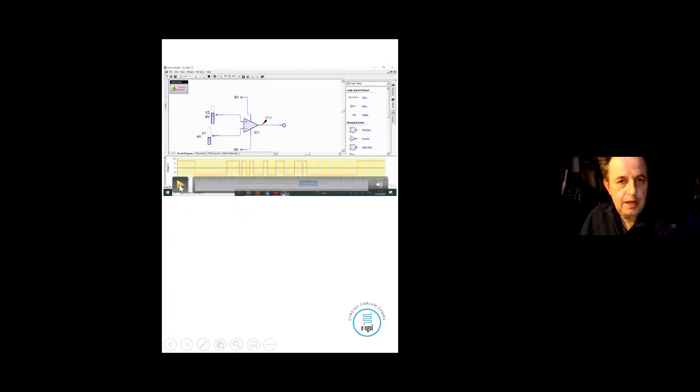First thing, basics of op-amps: please remember that with an op-amp, how it works, you basically have two terminals, the positive and the negative. If positive is bigger than negative, like now, you're in positive saturation, you've got 9 volts. If the input of the positive goes below, as it's done now, you've gone into negative saturation, so it's gone into the -9. Positive bigger than negative goes into positive saturation. Negative bigger than positive goes into negative saturation. So that's the basics of how an op-amp works.